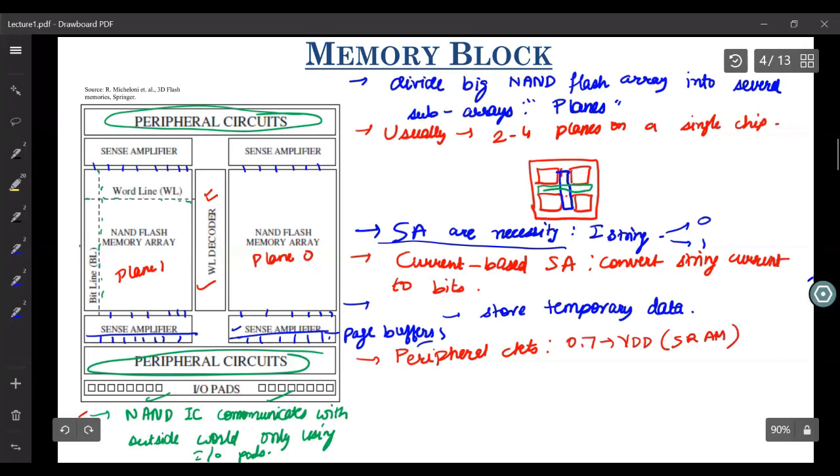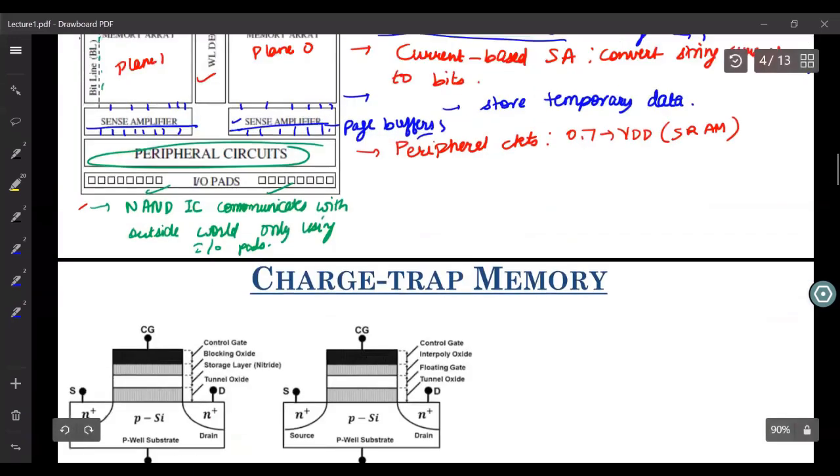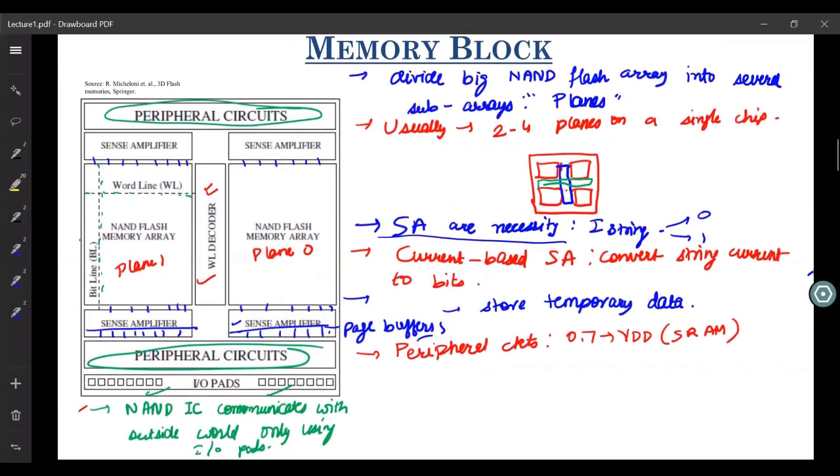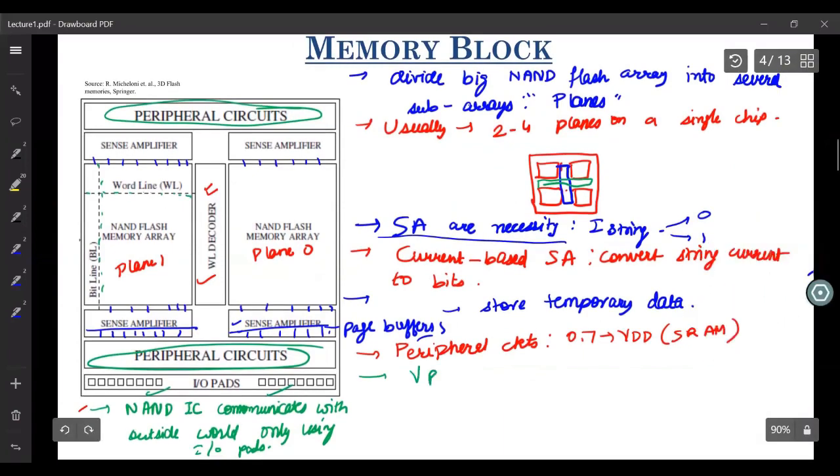However, the physical mechanisms that you exploit in your NAND flash array are CHE or FN. It's not CHE for NAND flash, but even FN is high voltage demanding. So the kind of voltages that you need to apply to program these devices: we program or erase in excess of at least 10 volts. So can your logic transistors handle 10 volts? No. Their oxide will burn out, or they won't be able to sustain these 10 volts.